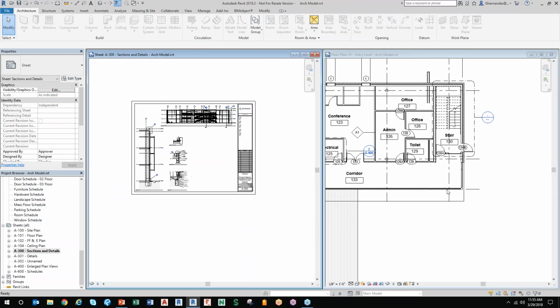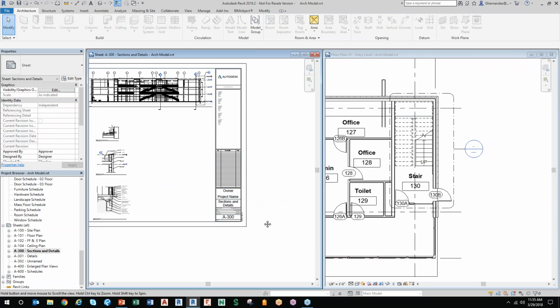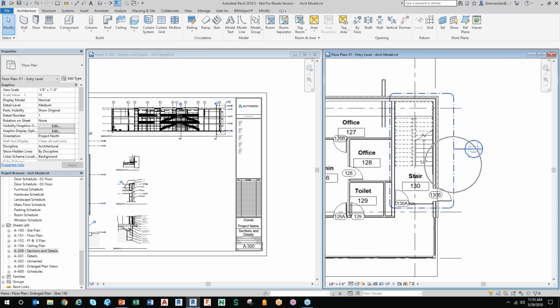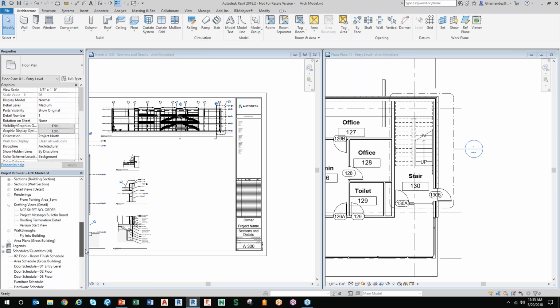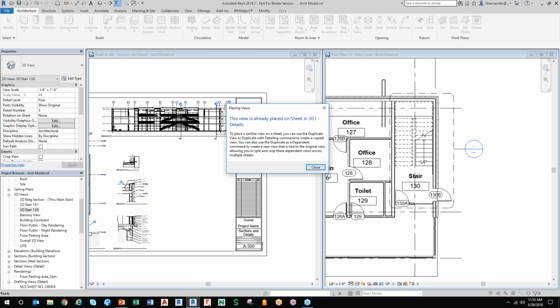So just like in AutoCAD, maybe I want a section view and a plan view and to design in that way, right? I can make multiple views or display multiple views. But I want you to look up on the screen here once I do this. This is where the mundane drafting tasks are gone in the Revit environment compared to an AutoCAD environment. Notice my detail here, my callout over here, my enlarged plan of my stairs. This is how you document in Revit, or create construction documents, which are basically a byproduct of the program.